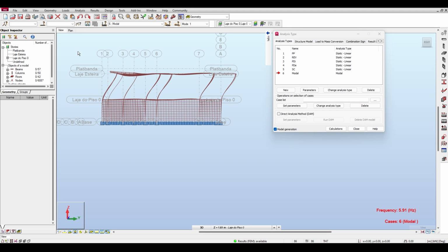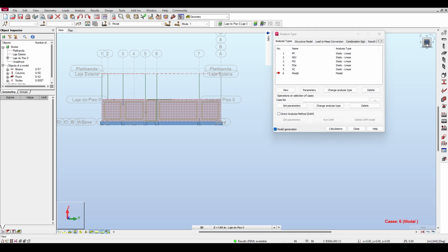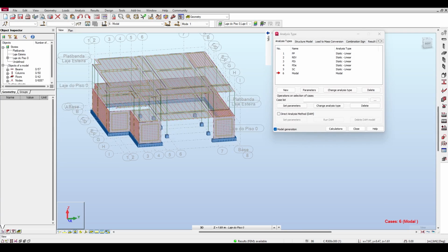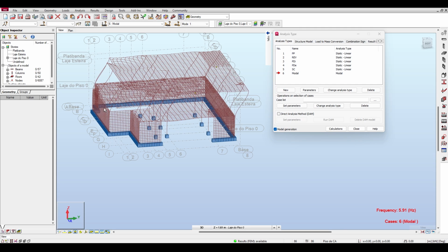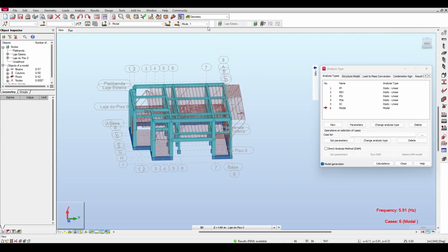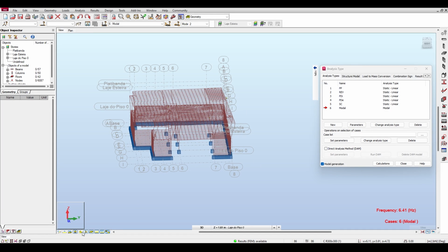Now, I didn't actually open the section so far for the structure, but immediately my prediction is that since the structure in the first mode is vibrating in the direction Y, the columns are going to be weak around X because it will vibrate in Y, right? So you can actually open mode 2 and study it very quickly, let's try to describe them before I continue, because I promised you I want to show you some cool stuff. So let me show you.